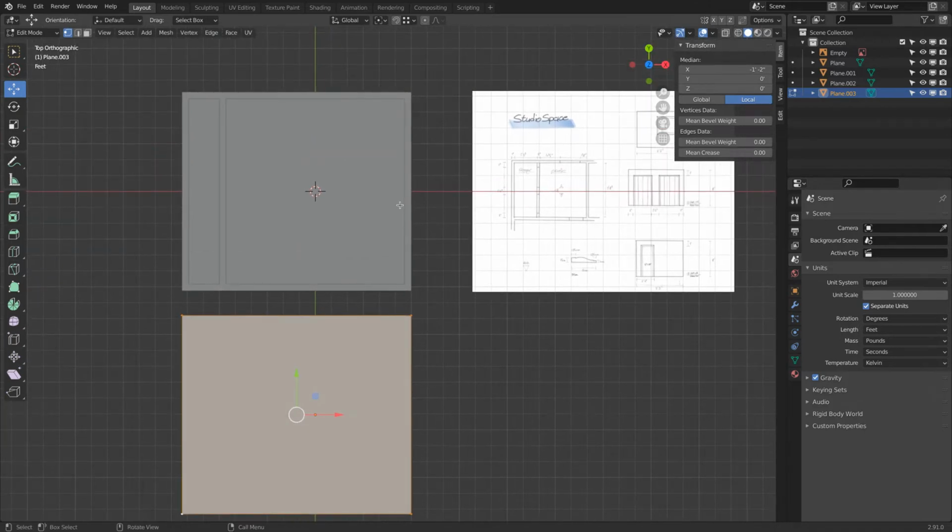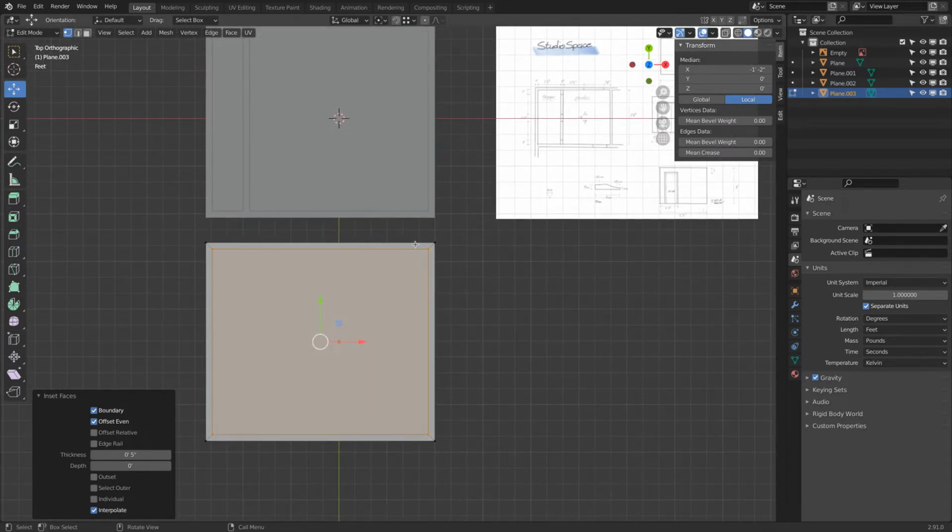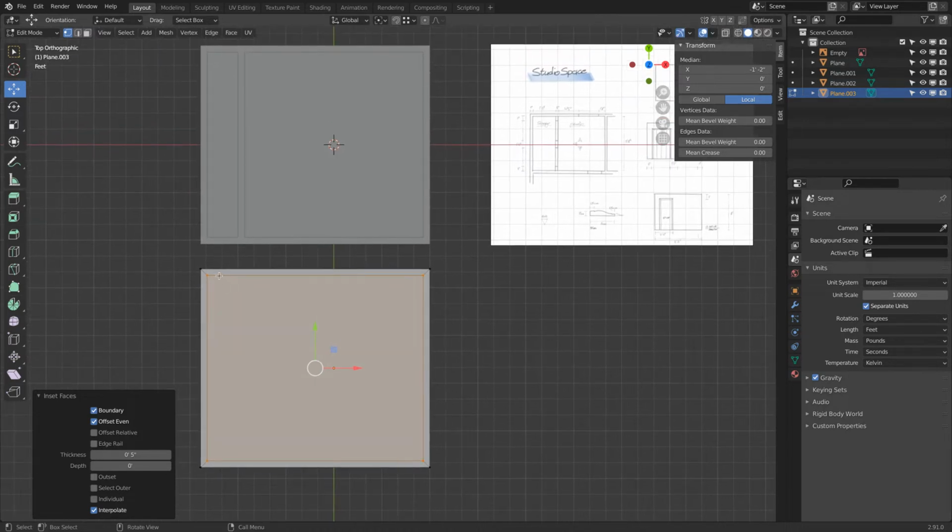So I basically created the exterior shape, and then to create the wall I can press I. There we are. Click, and then here we say 5 inches. Very good. So you see, via this method, it just creates with 45-degree corner lines the walls.